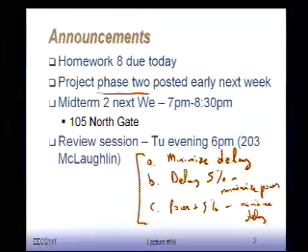As I said, everything's free game. You can change the... Well, not everything. The register cells remain fixed. We're not going to mess around with those. But you can redesign the other cell. You can definitely change the topology, the way you combine things together, how you hook all your cells together. All of this is free game. You might go for dynamic. You might go for a new logic style like adiabatic or something like that.